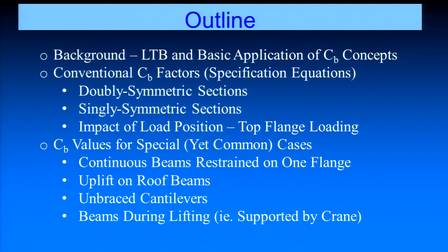Then we'll be finishing up by talking about C sub B values for special cases. I call them special cases because they're not necessarily in the specification itself, but they're actually very common cases. There are a lot of questions that come up as you're designing where you may ask yourself, is the C sub B equation in the specification actually even applicable? And we'll look at a number of different cases.